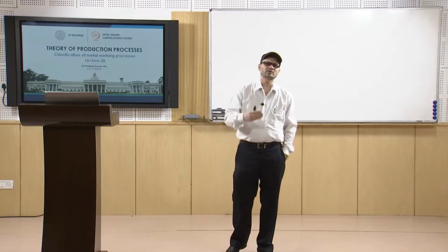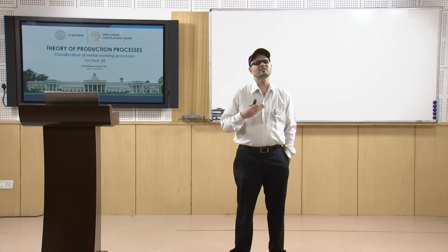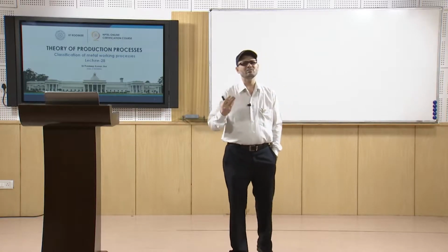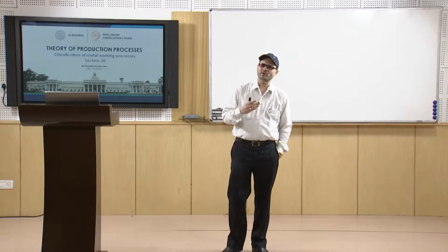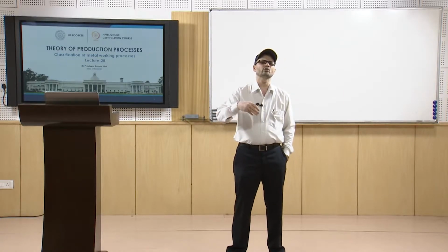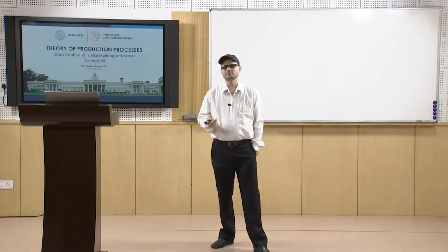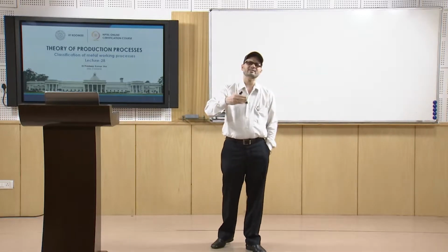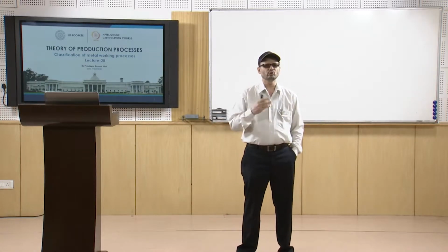Many a times the strength is improved, ductility is improved, fracture toughness is improved. Basically, we go for metalworking for improving the properties, and also for shaping in certain cases, but during that process the mechanical properties usually improve.